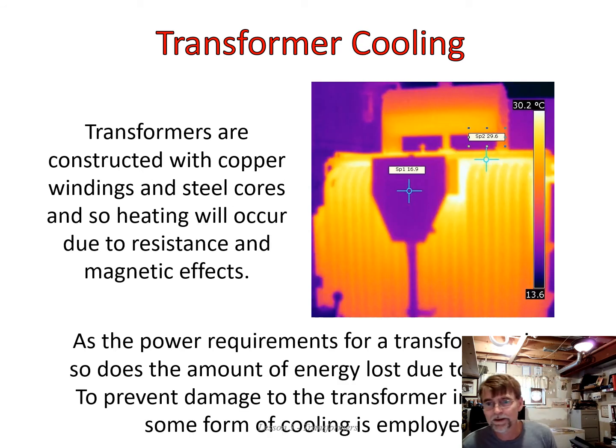So here's a nice picture. Anybody know what this is? This is an infrared shot. It's something that I've done a bit of in terms of evaluating an electrical installation and determining where or if any maintenance work is required. You will go in with an infrared camera and you will look for hot spots. Where there is excessive heat being generated, you have the potential for problems, and so you want to address this.